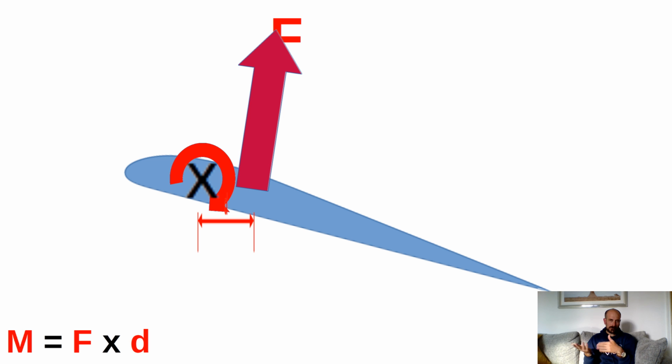Of course, when it gets close to stall and so forth, then it deviates a bit and the centre of pressure moves in a non-linear way and the lift is generated in a non-linear way, so this relationship breaks down. But for most angles of attack, this is a constant. Now, the moment isn't zero.